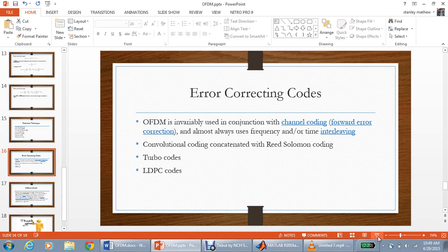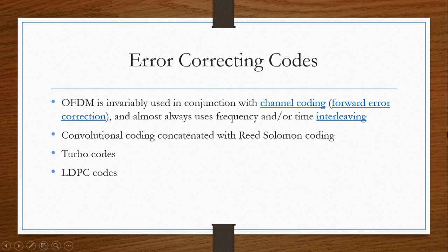After talking about frequency interleaving, let's go to time interleaving. Time interleaving is of little benefit in slowly fading channels, such as for stationary reception, and frequency interleaving offers little to no benefit for narrowband channels that suffer from flat fading.